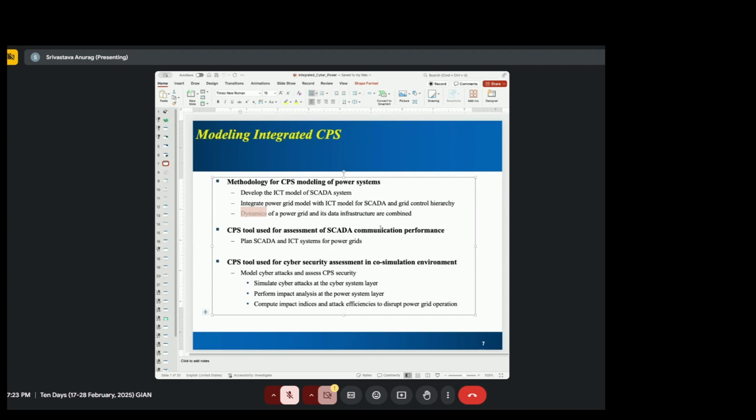If you are dealing with, let's say, transient stability, we are talking about milliseconds. If you're dealing with protection, we are also talking about milliseconds. If you're dealing with electromechanical interaction, like torsional impact, which will change the torque because you're increasing the load, you're slightly dealing with a little bit lower than a few milliseconds.